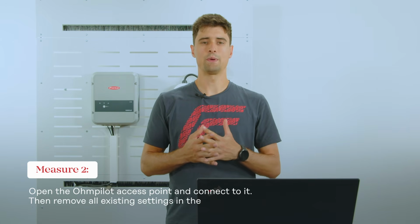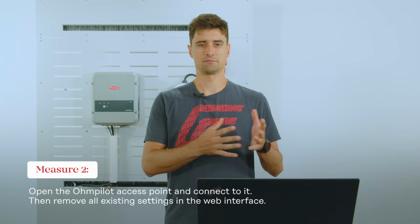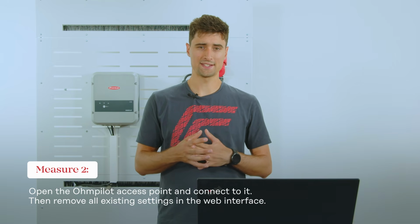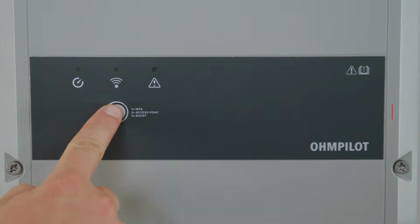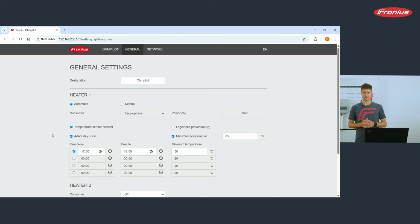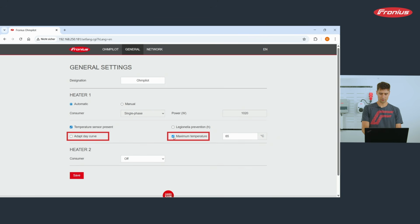Secondly, connect to the Ohmpilot interface and remove all settings regarding time and temperature. In order to do so, open the access point and press the touch sensor 2 times. Then connect to the web interface. When clicking on the point General, then you see below here Adapt Day Curve and Maximum Temperature. Remove both ticks and don't forget to click Save.